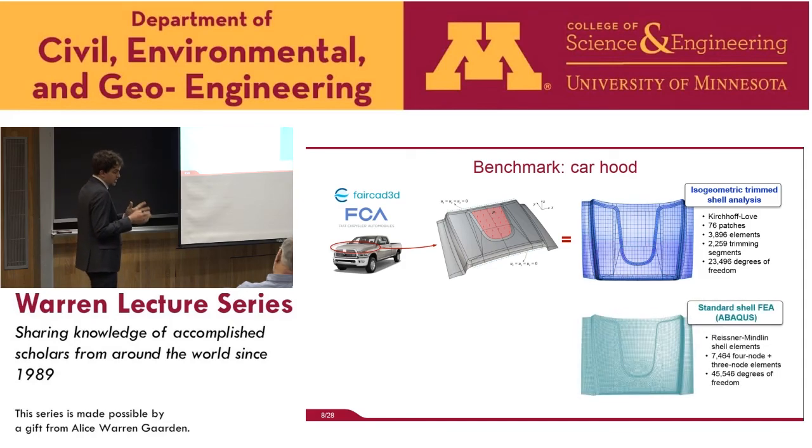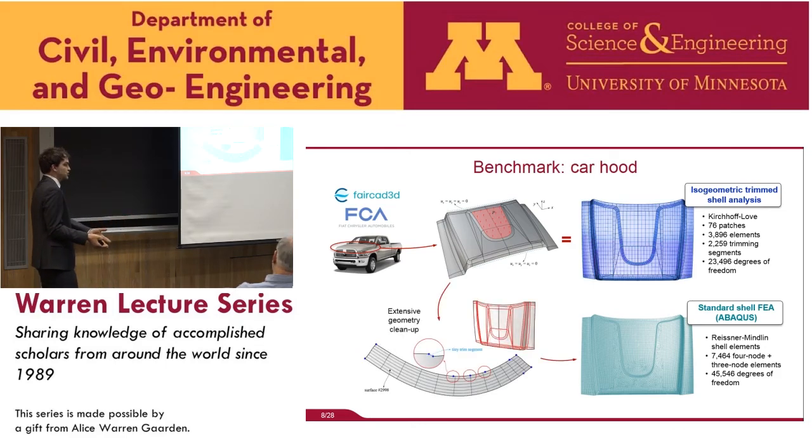If you compare this to the standard way to do this right now, you can look at a standard finite element code. This here is Abaqus, and here you would have to get a mesh, a separate geometry representation from this one. So you have to transfer this geometry representation into this mesh. For that, you have to use, first of all, geometry repair. So you load this geometry into Abaqus. It gives you this picture where each red dot signifies one geometric problem that needs to be cleaned. And for this relatively simple geometry, Abaqus can do that correctly.